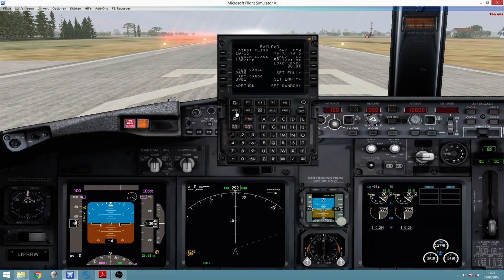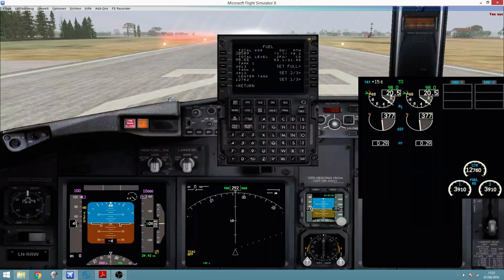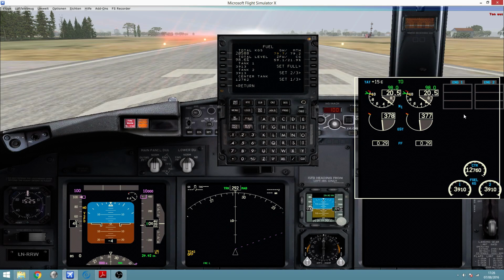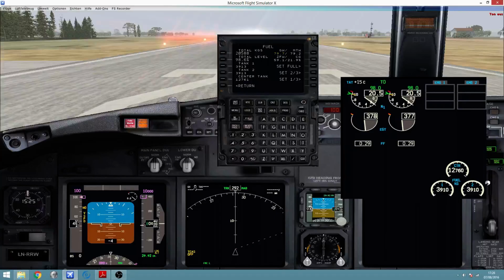Good. So you have to write down these values for your report, and I'm going to change the amount of fuel that I have on board. I go to menu, FS Actions, Fuel, and as I said before, on this screen you can read the indications of fuel that you have on your aircraft, and it's indicating that the central tank is totally full. I'm going to select 0 kilos of fuel for the center tank, so I press on 0 and then I introduce that value here.